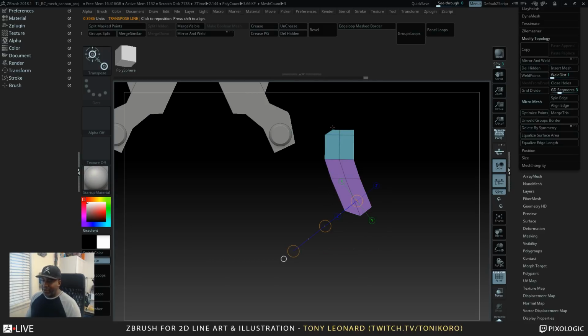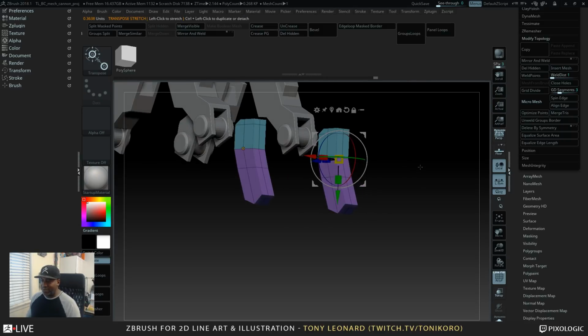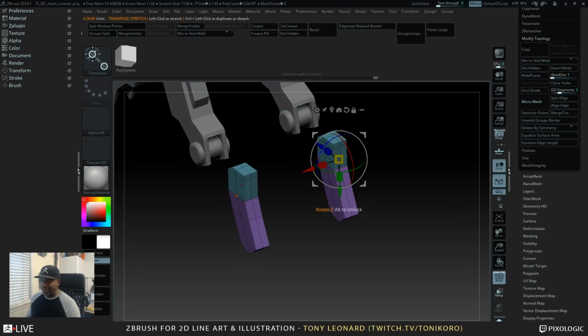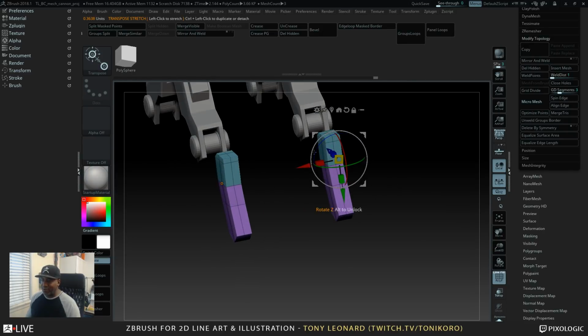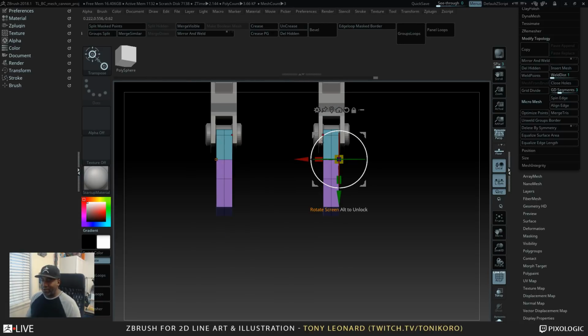So right now I'm just going to use transpose to sort of straighten this out. And if I hold Shift here and then hit W, it seems like it recenters it. The axis is a little topsy-turvy, but you can always hold Alt and just flip this, holding Alt plus then Shift, you can actually rotate this around.